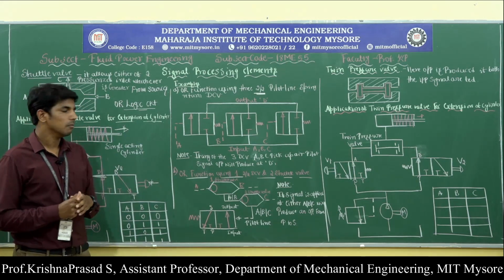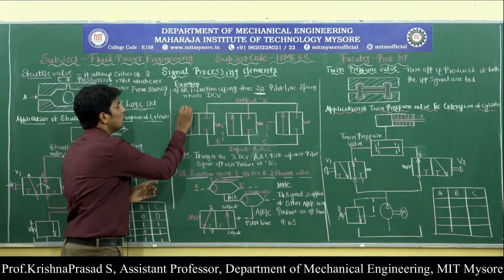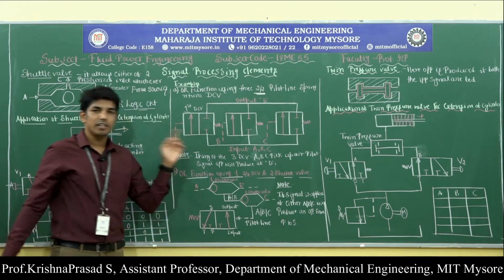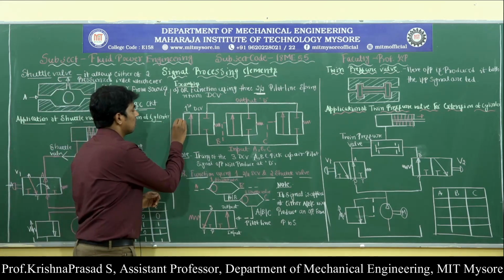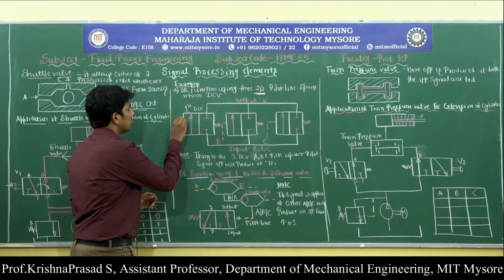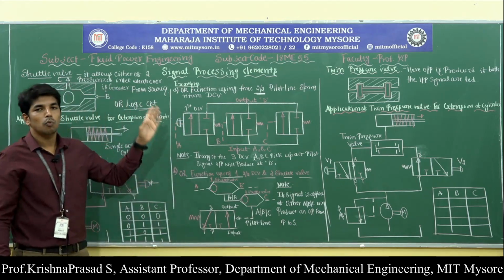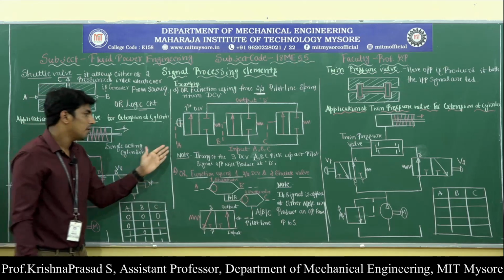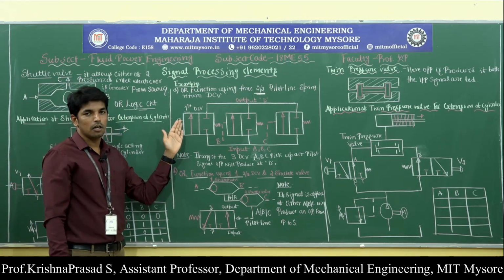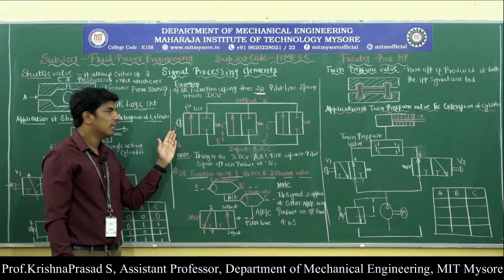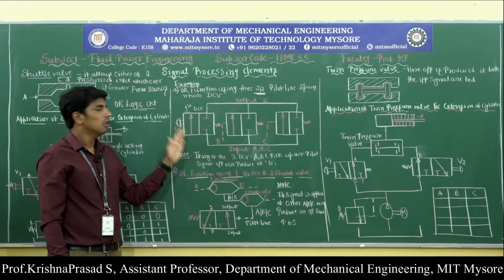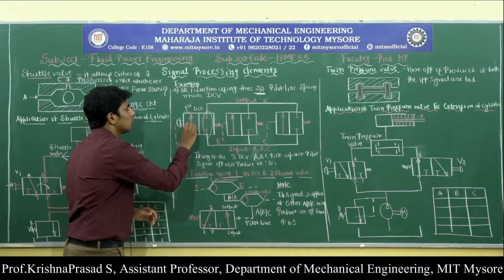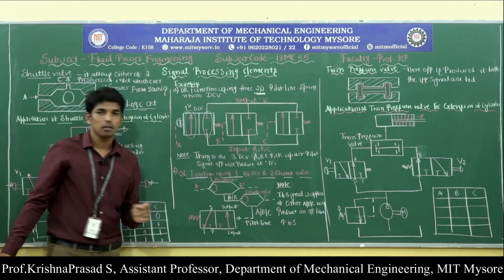There are 3 cases here. If the direction control valve 1 is actuated by pressing the push button, then compressed air will flow through the pilot line A, then it will actuate the direction control valve from the normally closed condition to the normally open position.